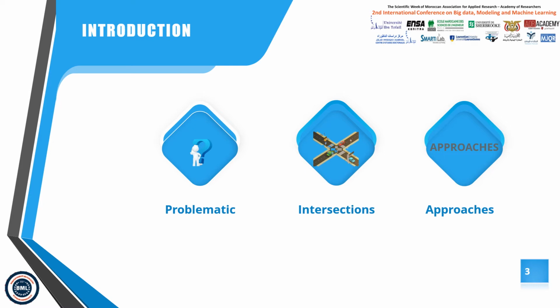In addition, Robertson developed a software tool called TRANSYT, which determined the optimal parameters for traffic lights at fixed times and calculated the performance index of the signal network. And we know other approaches such as basic right-of-way rule, stop or yield control, and signal control. And finally, we have another approach: speed control.